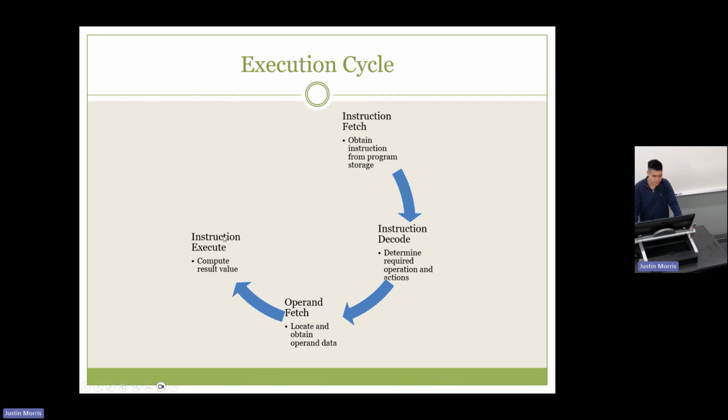Then when we have the operands, we can execute the instruction. So was it an add? Was it subtract? Things like that. And after we execute, we can write back our results. So this is either going to store the resulting computed result into a register, or it could be storing the results back to memory as a store function.